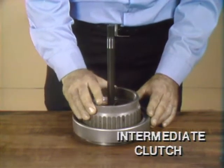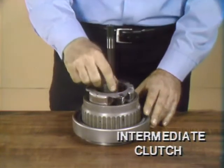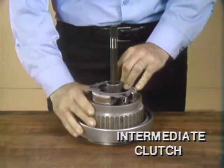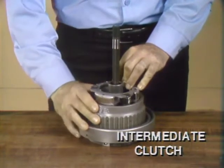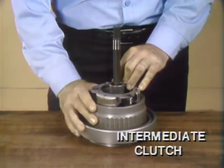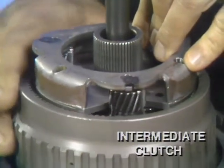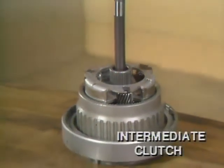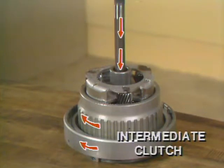This clutch is applied in second gear and in third gear, and when it's applied, the intermediate shaft drives the ring gear. Thus, in both second gear and third gear, there is power flow in through the intermediate shaft and the ring gear to the long pinions in the planet carrier assembly. Let's review that. In second and high gear, the intermediate shaft drives the intermediate clutch, which drives the ring gear, and power is applied through the long pinions to the pinion carrier.